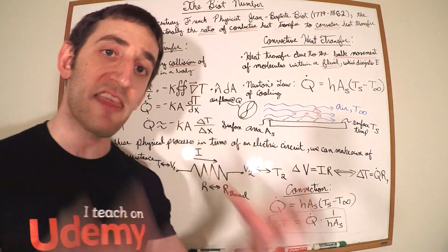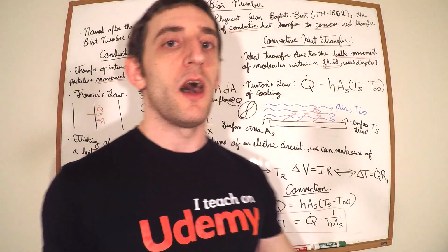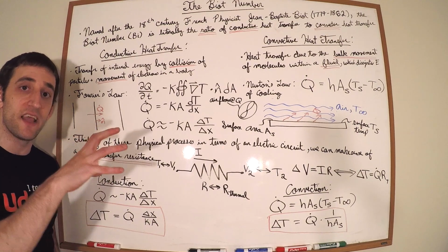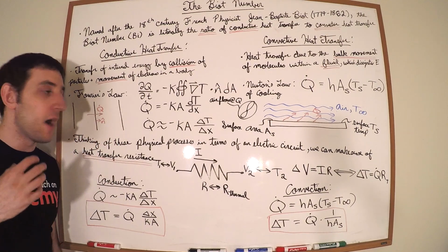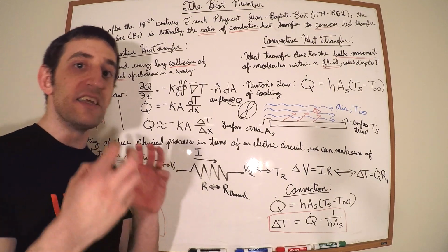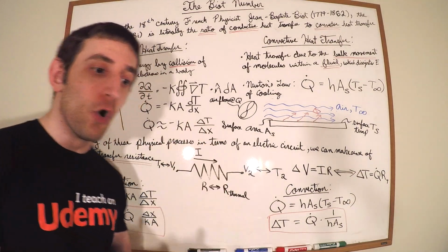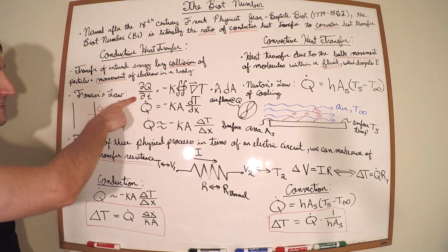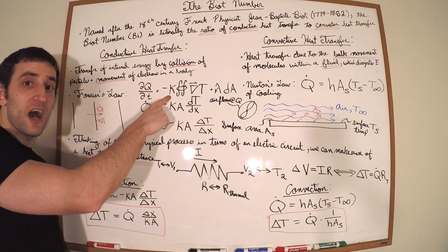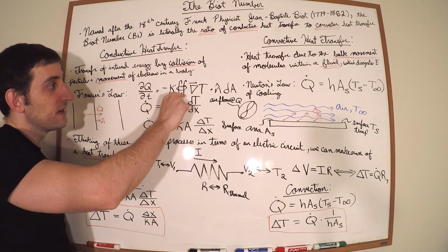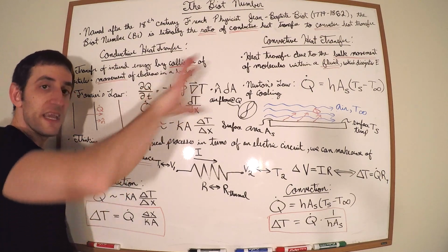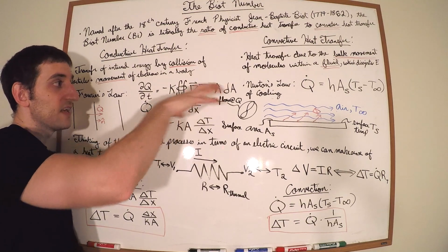And in terms of the mathematical description and the physics, Fourier, a scientist in the olden days, studied this kind of mechanism quite extensively, and he came up with a mathematical relation related to it, which is known as Fourier's law, which tells us how to determine and measure the heat transfer, or the change of energy per time, dQ/dt, and he defined that as a ratio related to a thermal conductivity, k, times the temperature gradient coming out of the surface over the entire surface.